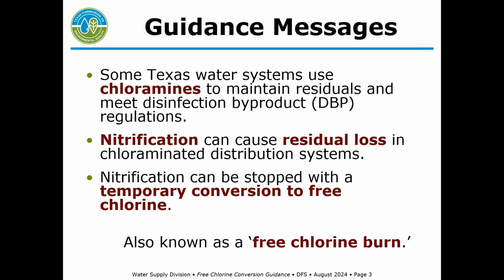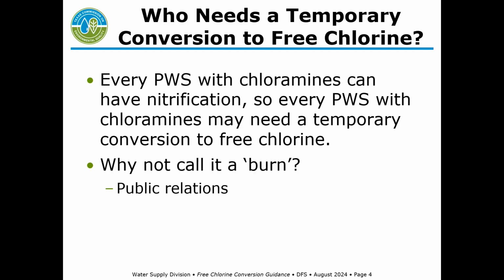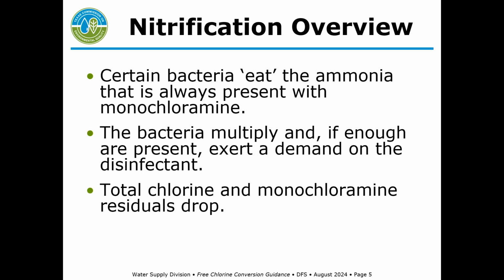You may hear that called a free chlorine burn. The second bullet here says, why not call it a burn? It's really better not to tell your customers you're burning their water. That's not what you're doing. You're just changing the residual type. If you don't want to call it a temporary conversion to free chlorine, I've heard things like doing a refresh. But for the most part, just for public relations, I would recommend you don't say that you're burning the water. As we said, any PWS that has chloramines could have nitrification, and so anybody with chloramines could need a free chlorine conversion.